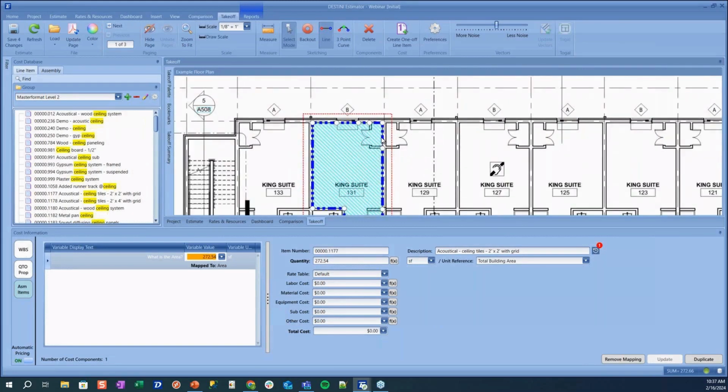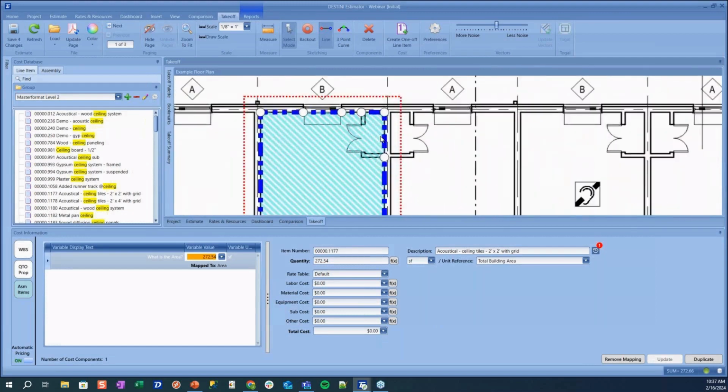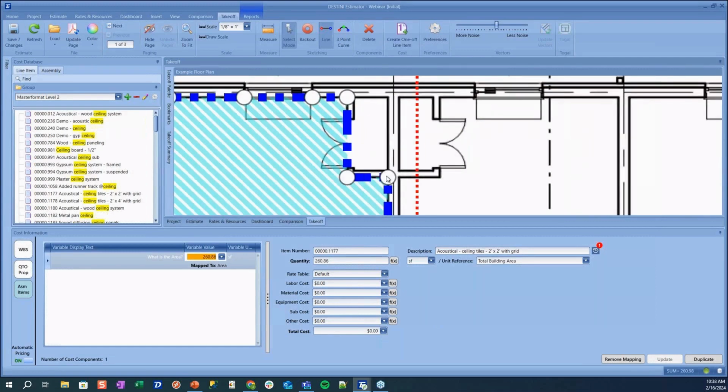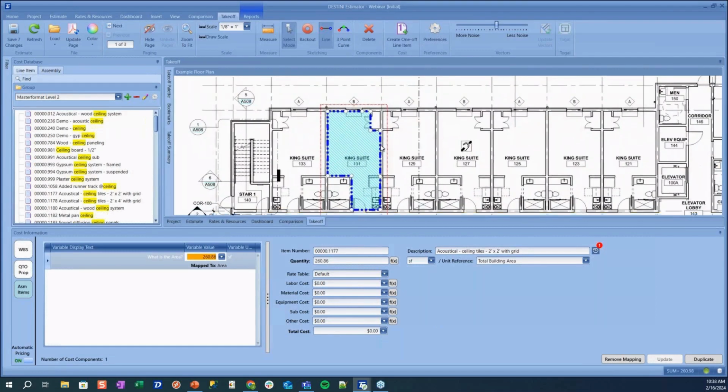Our first step there is we're going to just left click on the takeoff that we want to add an additional point to. We can right click and select the add point button, and we'll add in another point to where we can drag our takeoff to. So here we'd have the ability to start to drag our points over. As we're clicking on those points, we can move them over, and now we have excluded our closet from our